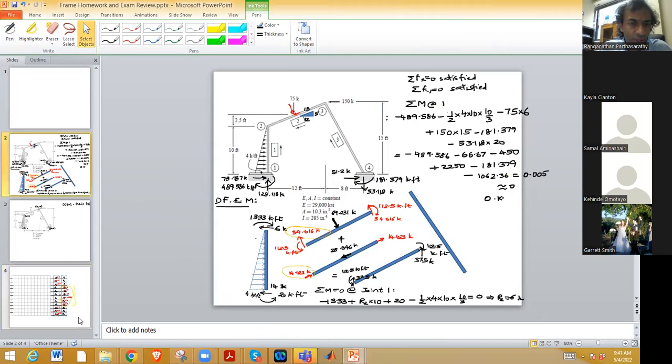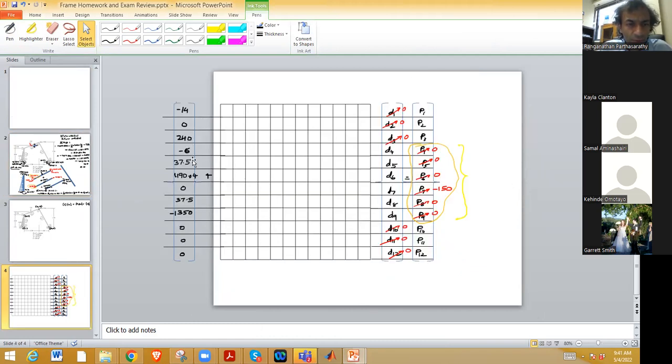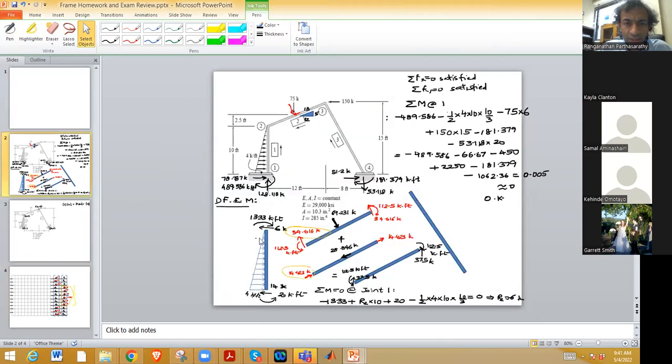Look, which joint is this? 1, 2, 3, 4, 5, 6. So second joint, the moment at the second joint, right? See, this is 13.33 clockwise, but for the member 2 at this joint, you have counterclockwise 112.5, right? So counterclockwise 112.5, that is positive 112.5, negative 13.33. How much is it? 112.5 minus 13.33. 99.17. You convert to kip inch, 1190.04, right? Yeah. Thank you. Okay.